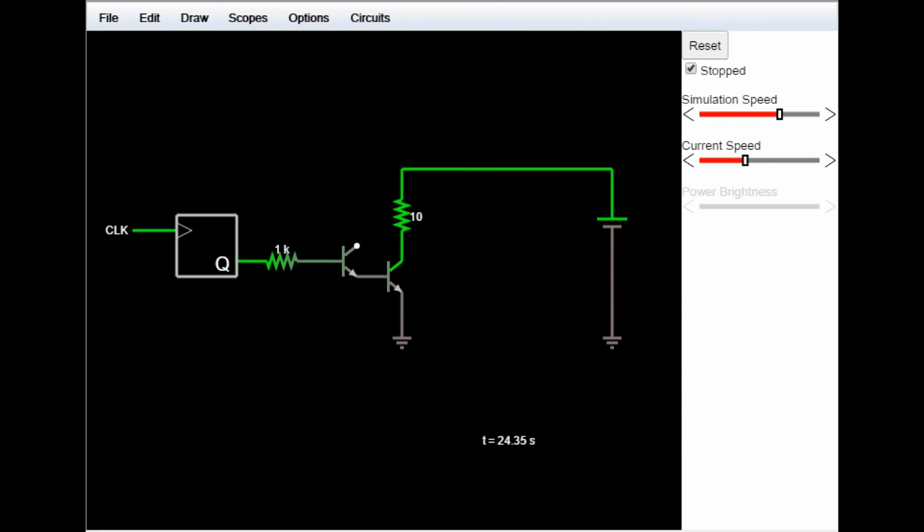I'm going to stop it just so I can set up the circuit. So here's our live wire, and I need to power this transistor, and I'm not going to use a wire for that because that would be a short circuit, right? So we need a resistor here. We can experiment with values for these two resistors in this new setup, but let's take a look at what happens when I run this. The current going through the motor is now exactly 1.2 amps. The current coming out of the microcontroller is 3.55 milliamps.